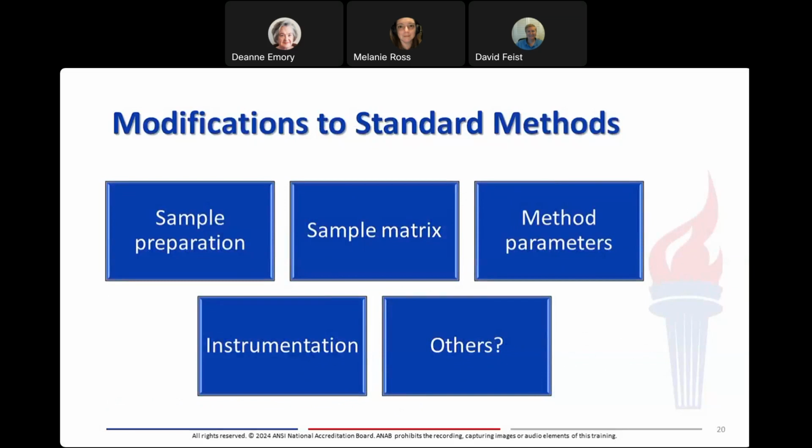There may be others. Note 1, after clause 7.2.2.1 in ISO 17025, cautions that validation can also include procedures for sampling, handling, and transportation of test and calibration items. ISO 17025 uses an example in one of its notes that a measurement procedure ordinarily used for measurement of mass concentration of nitrogen in water may be validated also for measurement of mass concentration of nitrogen in human serum.